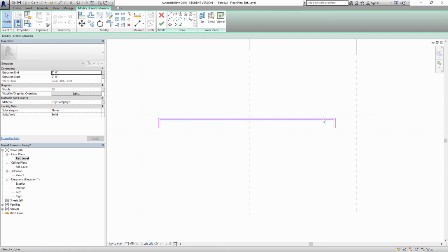And lastly, I'm going to snap the outside to our reference lines so that if I ever move a reference line, our panel extrusion profile will move too. So using AL, I'll align to the left reference plane, my left line, and lock it. My front to, well, this is the depth plane, gets the front, lock that.